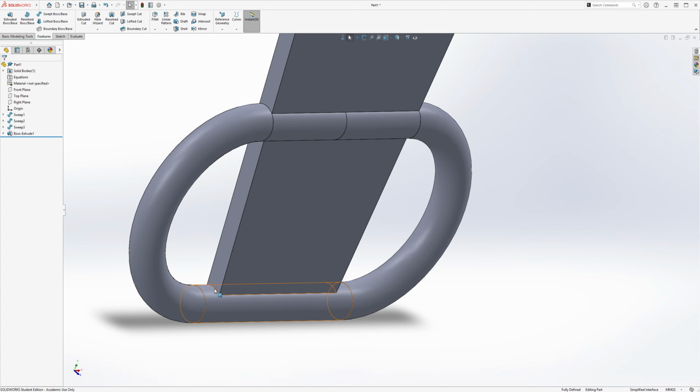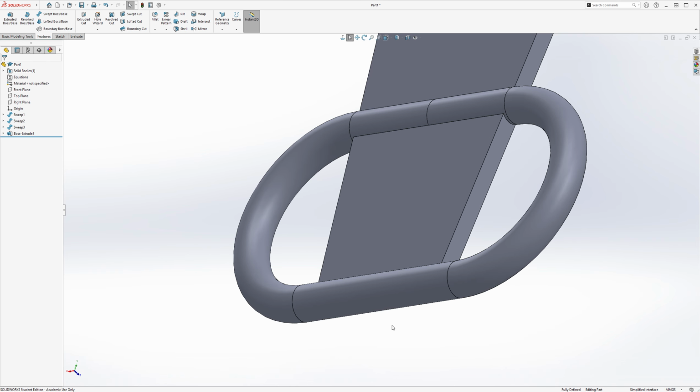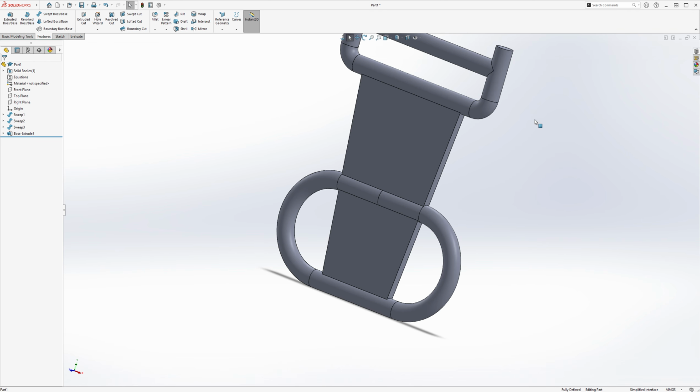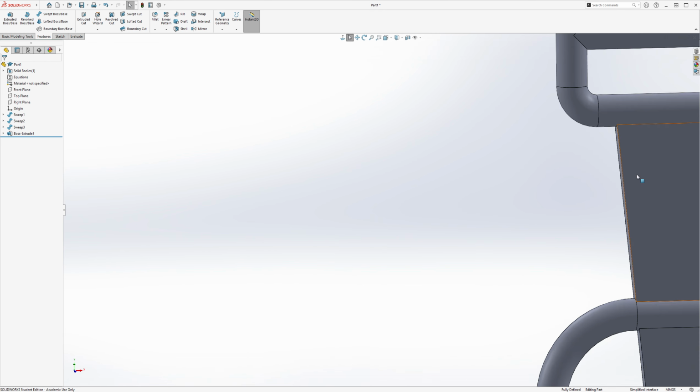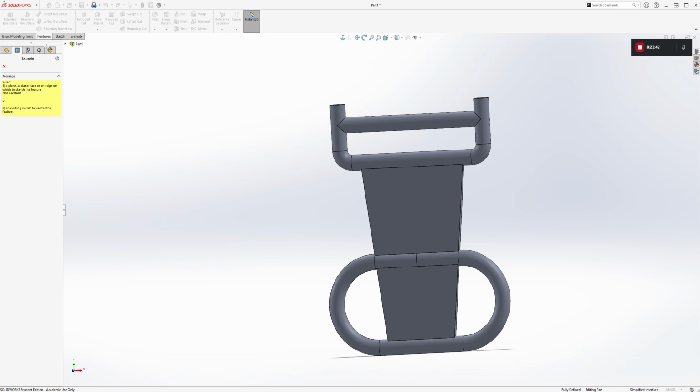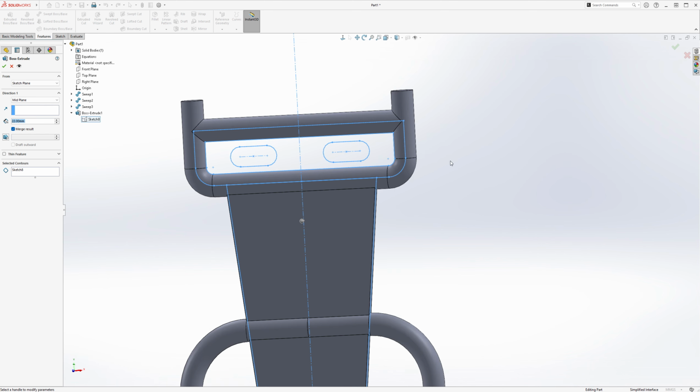So check for any pockets. See how it goes through the sweep without actually breaching it on the other side. No air pockets whatsoever. This side too is perfect. And then we'll finish the extrude by space, go to the same sketch, do the other side, but this time it has a thickness of 6. It's much thinner than the Dorito.